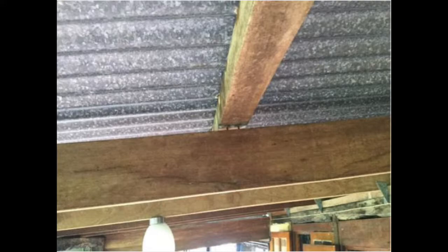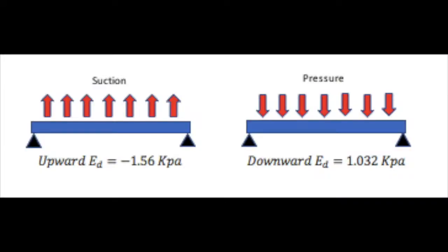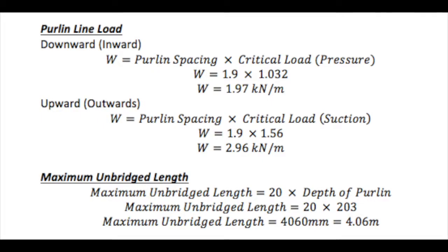Testing has been conducted to prevent major damage to the roofing and structures. To overcome damage to roofing and structures themselves, we calculate the greatest possible upward and downward pressure to then use the most economical materials possible. We completed this and found the most severe design combinations, as it was important to consider the worst possible scenarios. This is identified as the purlin line load.